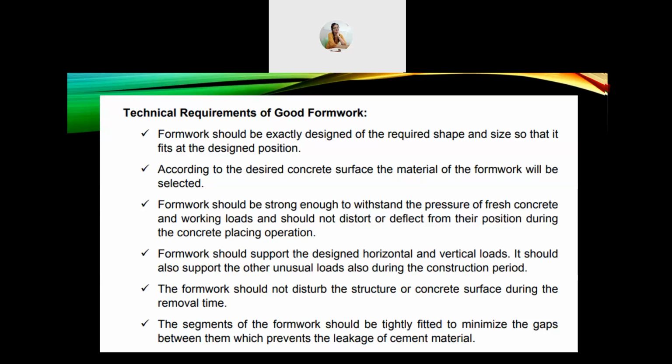4. Formwork should support the design horizontal and vertical loads. It should also support other unusual loads during the construction period. 5. The formwork should not disturb the structure or concrete surface during the removal time. And the last one, the segments of the formwork should be tightly fitted to minimize the gaps between them, which prevents the leakage of cement material.